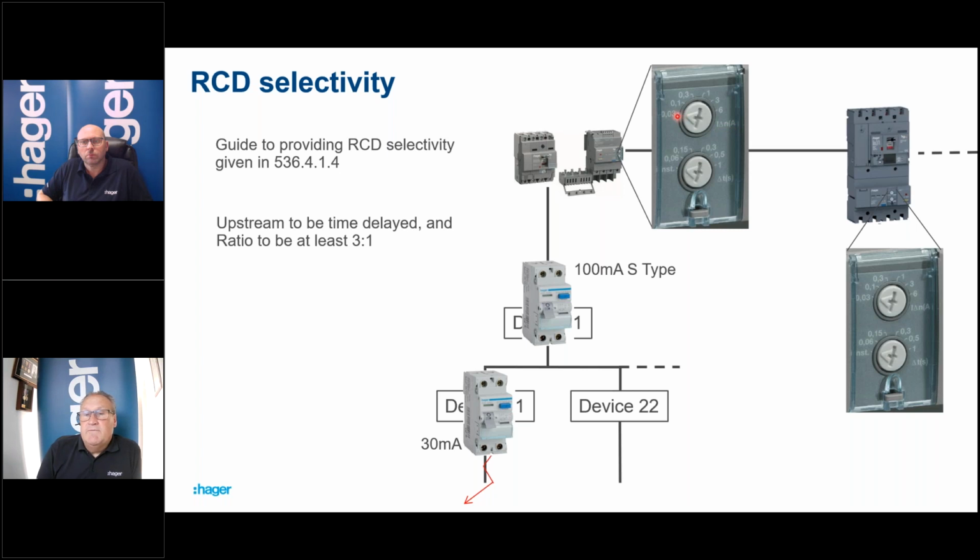At the moment it's pointing to 30 milliamps, and it can go all the way around to 6 amps. So that gives us the current adjustment. And the bottom dial here, you can see a time adjustment, delta T in seconds. So either instantaneously, so no time delay, or we've got 60 milliseconds, etc., all the way up to a 1 second time delay.